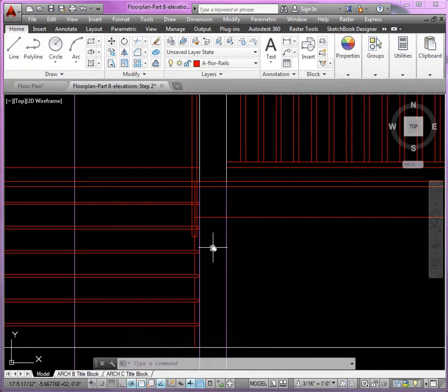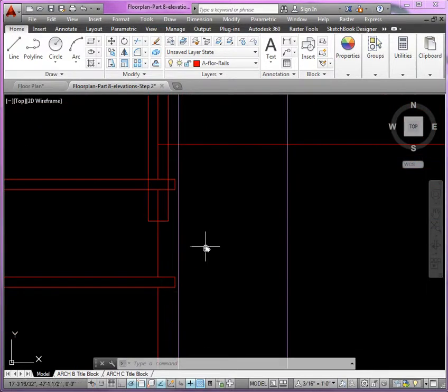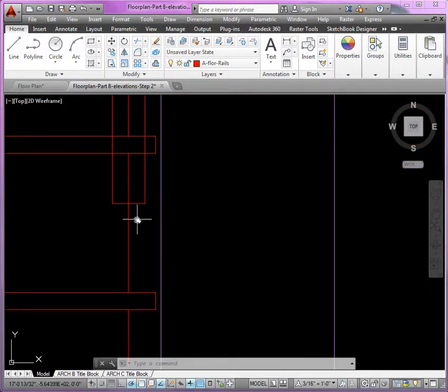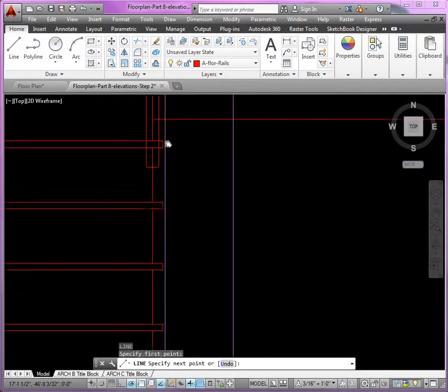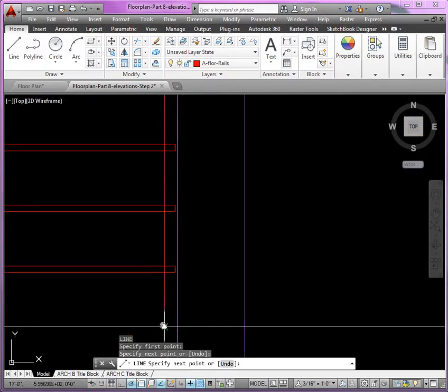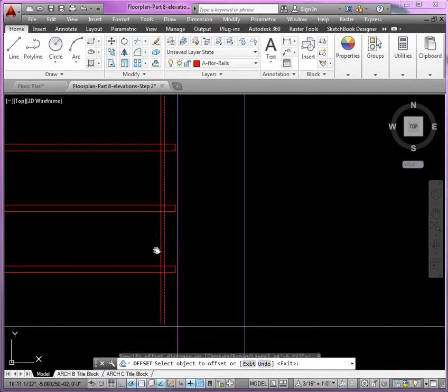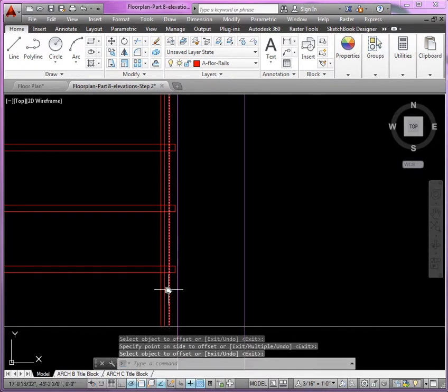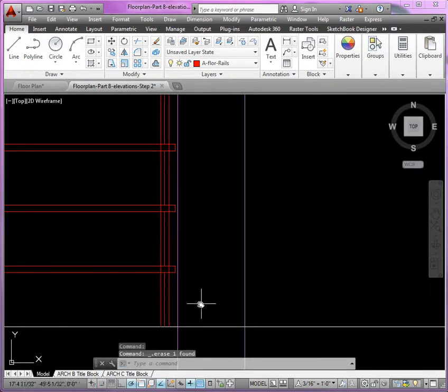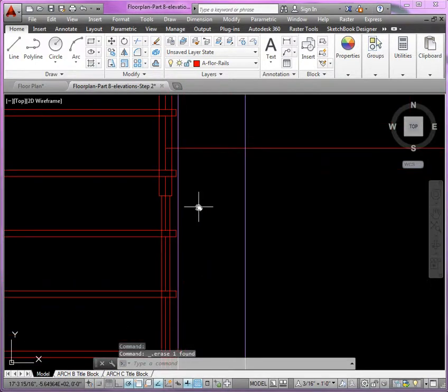Now we've got a bottom rail there of 1 inch. So here we could do a couple things. If I find first the midpoint here, you can just bring it all the way down and then offset to either side 1/2 inch, offset to either side 1/2 inch, and then go back and delete that line. So there's that railing there.